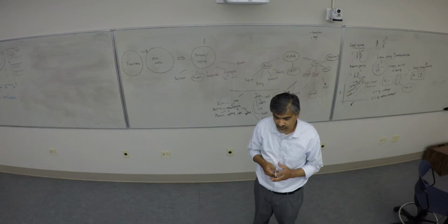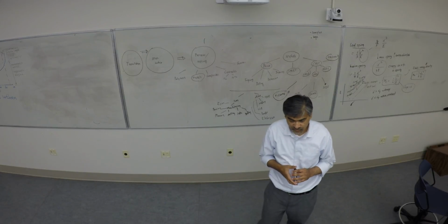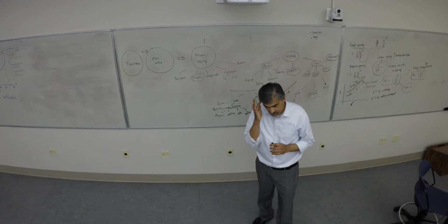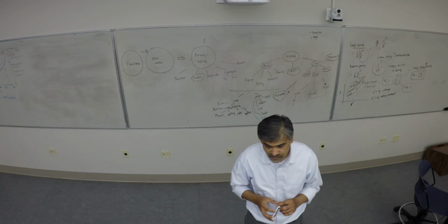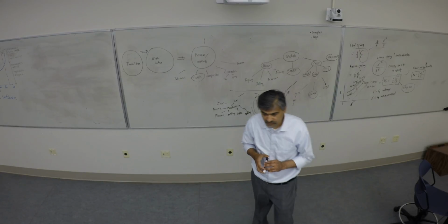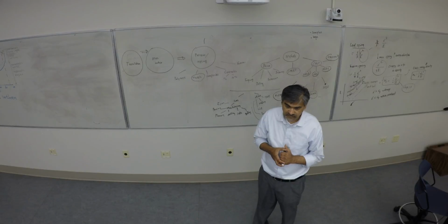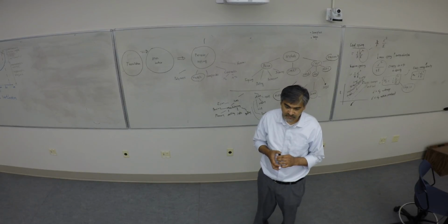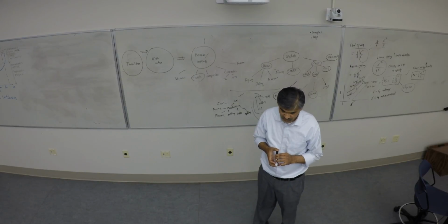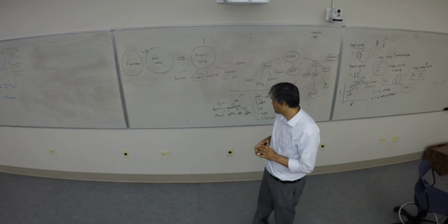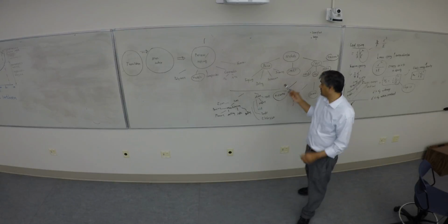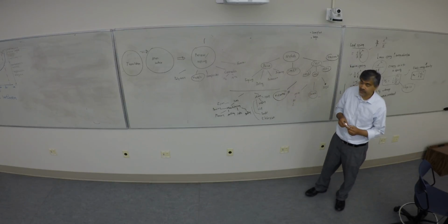I think the border gets fuzzy, right? Because there's not a strict breakpoint between additive or subtractive. So a lot of times you classify things like that as simply a finishing operation, and you don't worry about whether your process is additive or subtractive. When you go subtractive after an additive operation, it's usually when you're feeding it into a traditional machining operation, where a lot of parts establish the final dimensions, very true of cast parts.